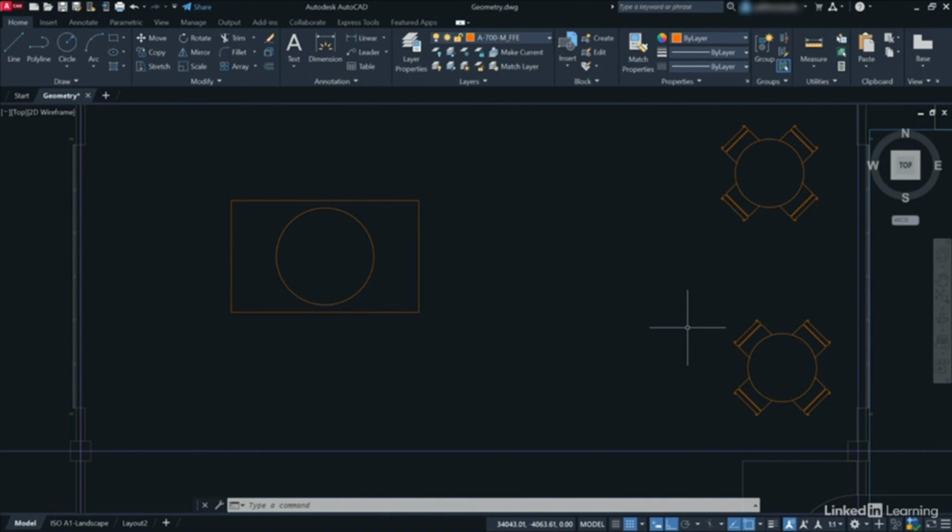So what I'm going to do now is go back to my line command up here on the draw panel. There's the line command. Come into the drawing area and I'm going to pick a point about here again, like I did last time. So it's a left click. And now when I move the mouse, you'll notice, can you see, I can only go up and down like so. I can only go in those directions, unfortunately. So basically what I'm going to need to do now is just move upwards. And again, I've got a distance. So I put 1500 in and I press enter.